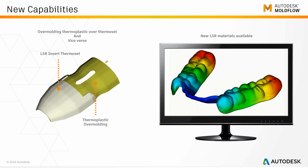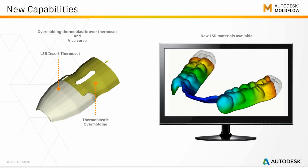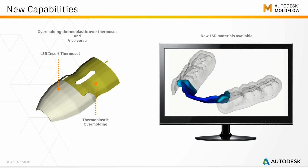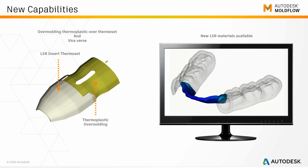Another thing that we fixed this time around was the ability to have a thermoplastic insert in a thermoset overmolding scenario, or if you have a thermoplastic overmolding scenario, you can now also assign a thermoset as a part insert. In prior releases, if you wanted to do a thermoplastic overmolding, you only had access to a metal database for inserts, or plastic database inserts.